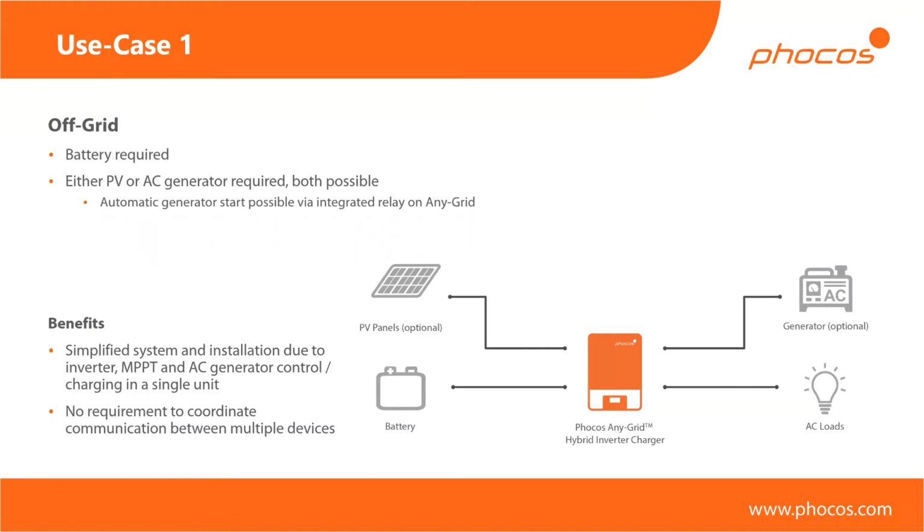Can the inverter rely on one power source only, the PV without AC or battery? Yes. Again, that is something we don't recommend. You can work with only PV and no AC and no battery, but that would be an inherently unstable system because there's just no storage anywhere. There's no alternative energy sources. So all the inverter can do is turn off if your PV power is lower than your load power. So it would work, but we don't necessarily recommend it.